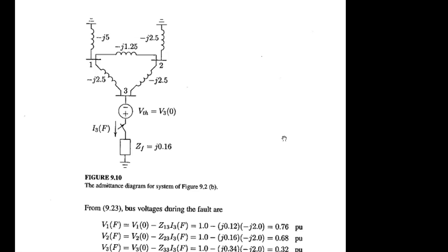Initially it was okay with Thevenin equivalent, but if the circuit is complex, in that case it will be difficult to address with Thevenin equivalent. I mentioned that thing when I started the discussion of the bus building algorithm, why you have to use it. Probably Tasin asked me this question, if you can recall. Z bus building algorithm, why should we use Z bus if we can manage it by Y bus inspection? But if it is addressed by bus building, it will be more convenient for you to address that issue. But sometimes it is required to check your Thevenin concept as well.